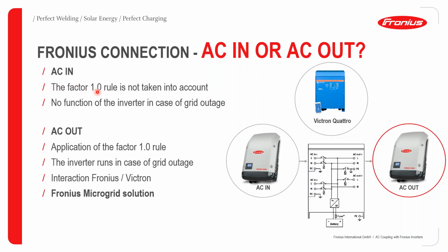Here, the design rule, as you're going to see later, as far as the design factors are concerned, what we refer to as the factor 1-to-1 rule, is not taken into account. And if there is a grid outage, because in this case, most likely there is going to be a public grid available, if there is a grid outage, then the Fronius inverter does not contribute to the power requirements for the duration the grid is out.